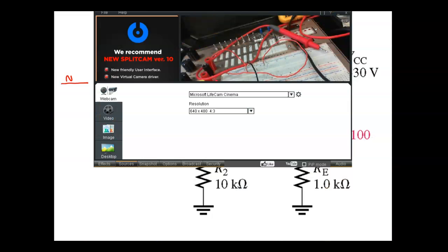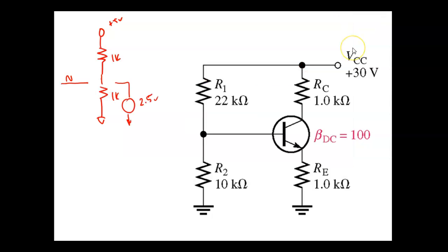So if I came over here and brought my AC signal in, even though I'm sitting right here at 9.4 volts, this would drop to 0, and the 22K would drop all the volts. So a DC source sees an AC source as a straight piece of wire, and vice versa. I just demonstrated that.